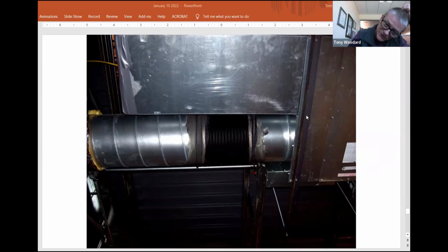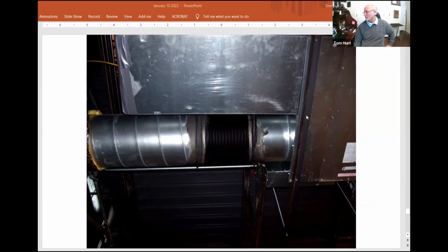This one was at a Votech school down in West Memphis, and the contractor that lost the job filed a complaint and wanted us to go back. He said that flex connector wasn't a rated flex connector. It does have a rating. It didn't quite meet the flame spread. It was a little higher than the 50. So the contractor that did the job, I told him, well, there's an easy fix. So we just full wrapped around that to meet the flame spread and we met the criteria. Me and the fire marshal, we signed off on it and went on.